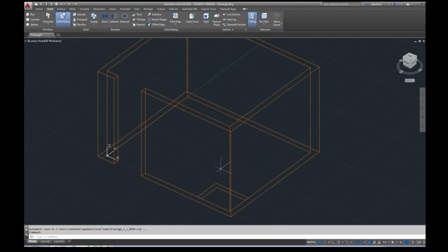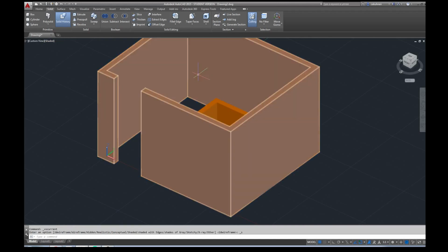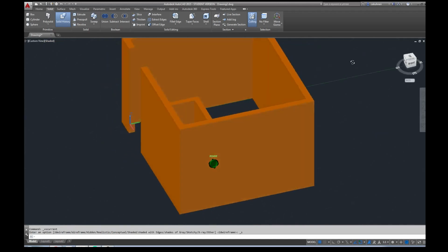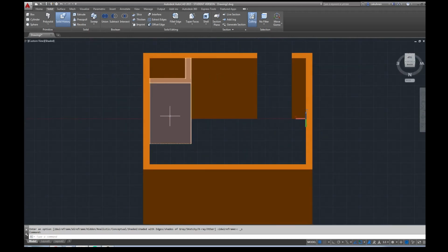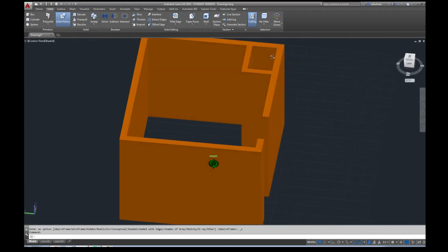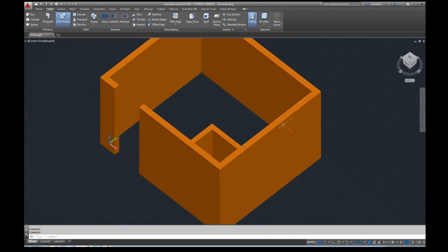You can do the whole extrusion one more time. Click on this object, spacebar, and then maybe snap here to this height point. Let's switch to shaded and take a look at what we have. So that's, for example, now our object. So you see a solid wall where we later cut a door into, and there's a door where everything is open.